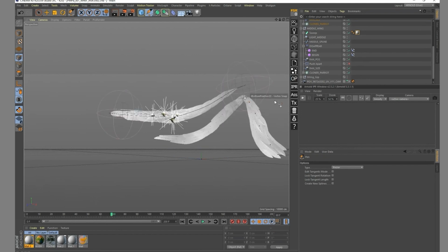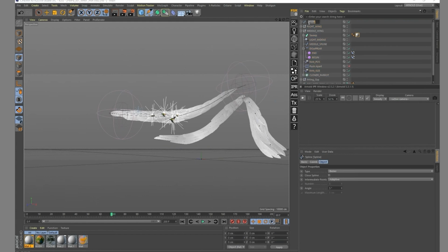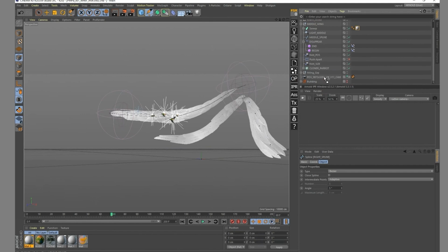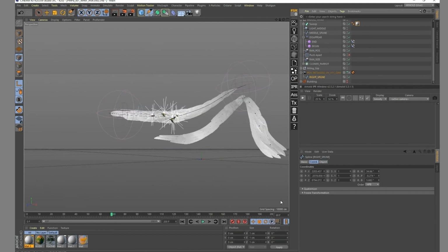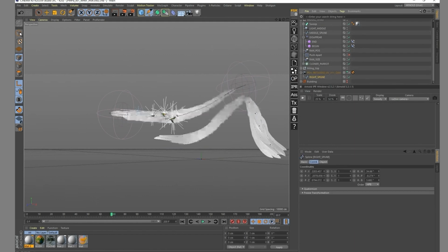That's it. It's the right spline. As we did before, I'm just gonna put that inside of my camera, activate the enable modification axis and change the coordinates of my spline to be 0, 0, 0. Deactivate that, going back in the right folder.